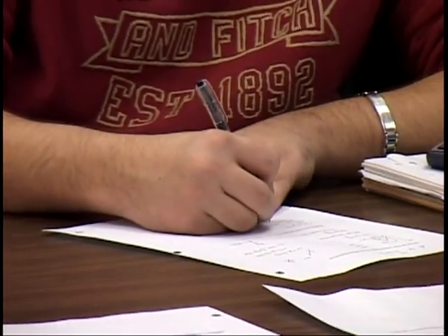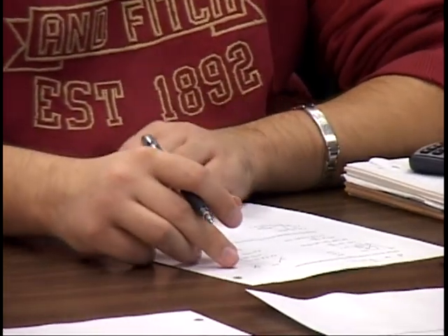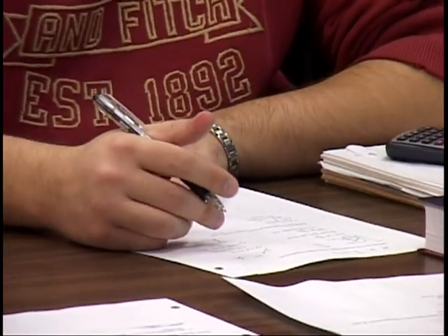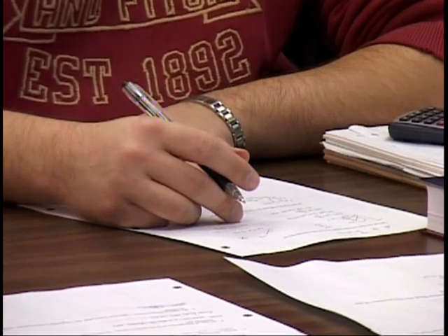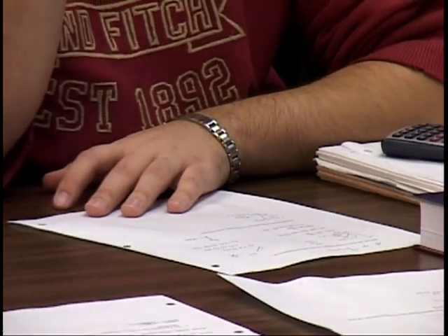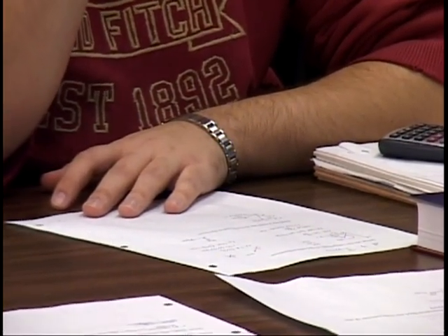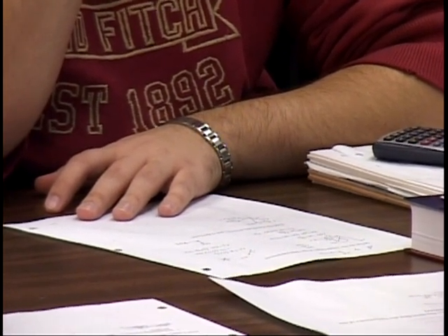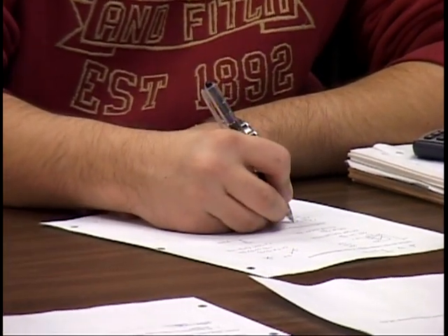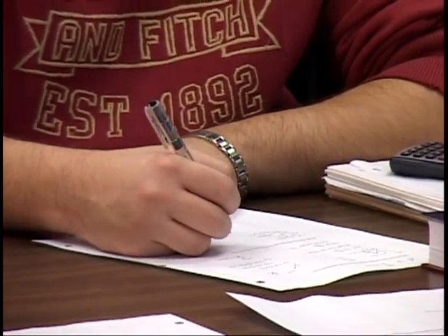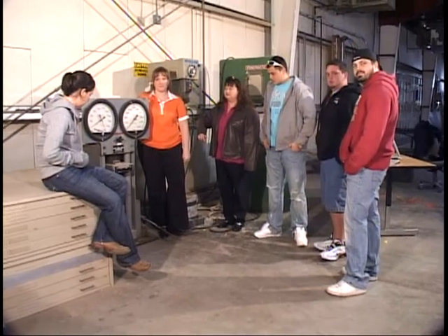So for force number 1, to get the x component, this is a 10-degree angle, and the x component is opposite of that angle. Which one are we going to use? Opposite, adjacent, tangent? Opposite would be sine, because we know the hypotenuse, right? Remember, the force is the hypotenuse. So when we find the opposite, we'll be finding the x component.